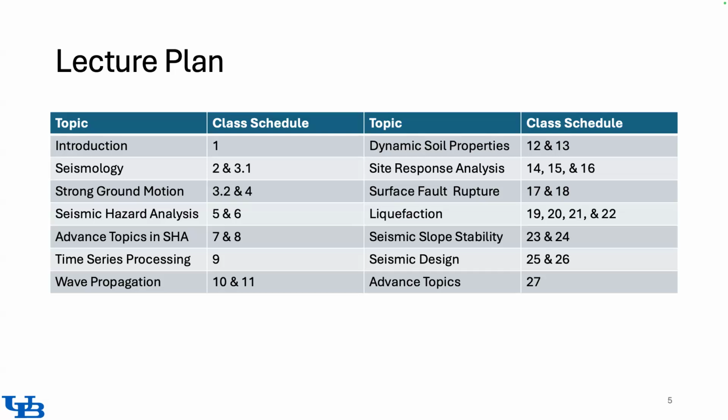Then some advanced topics on seismic hazard that are more related to ongoing research, the open questions, and how we are trying to address them. We will spend a class on time series processing and how to select time series for dynamic analysis, or how we can modify them if we don't have good recorded time histories.